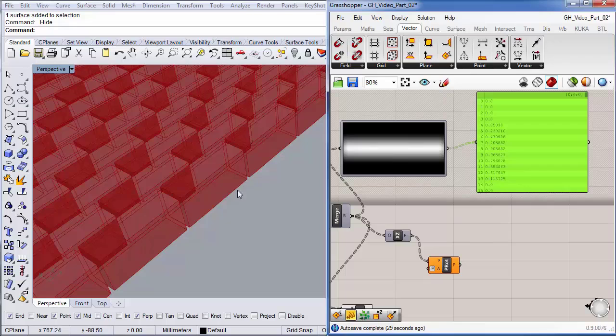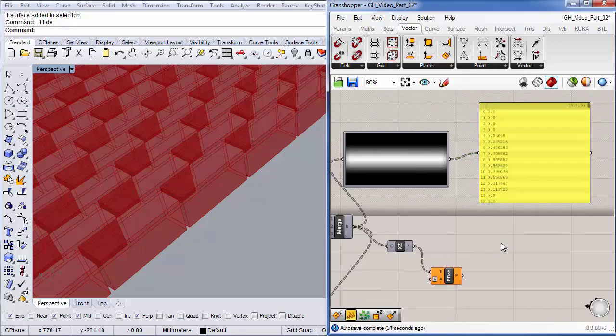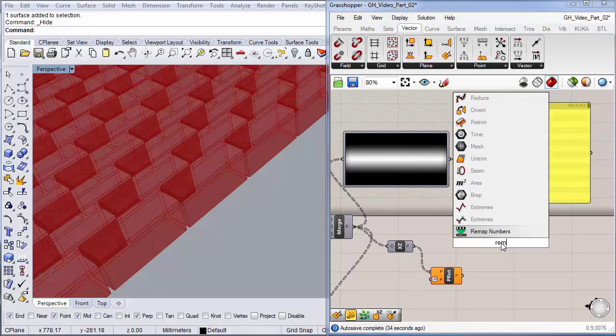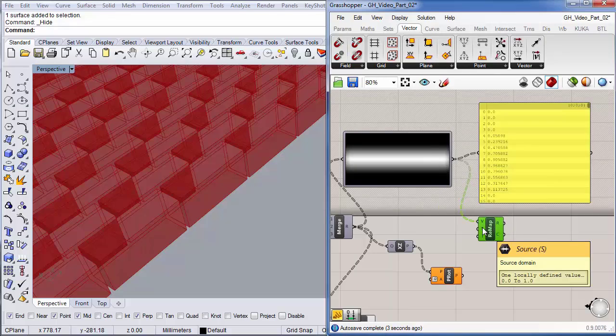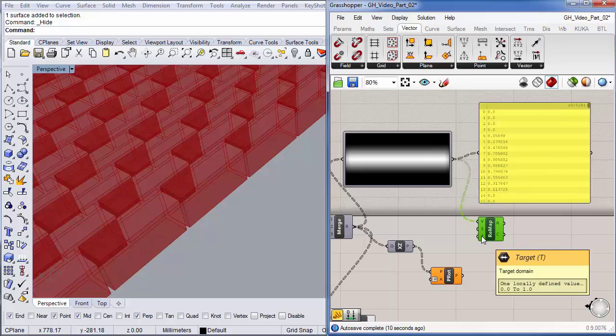If I rotate this thing at 0.7, it's not going to rotate at all. So we can do that with something called a remap. We're going to remap a set of numbers. We're going to take all of these values as our input value and remap them. You can see nothing's really happened because the domains are the same. It needs a target domain. In essence, we're going to give it a range to remap, so we're going to say remap those numbers anywhere from 0 to something else.